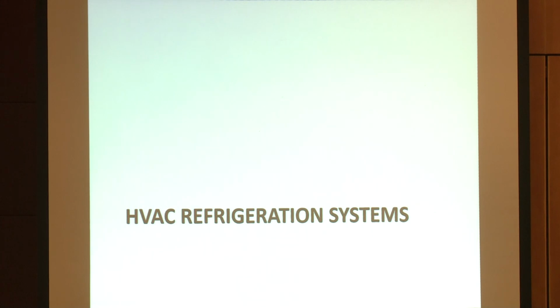The other thing we do on buildings is we have a lot of chill water systems, we have a lot of large DX systems, but we also have a lot of small refrigeration systems. The TAB work on small refrigeration systems is really pretty small because there's not a lot that you can adjust on it, but it's important to document it and make sure that we have everything listed on a piece of